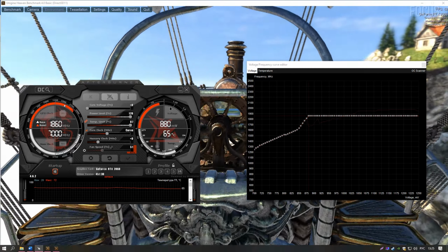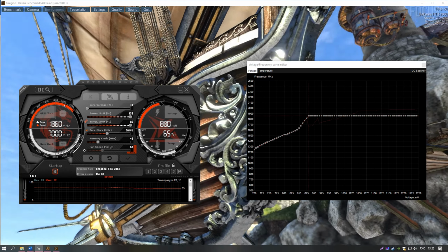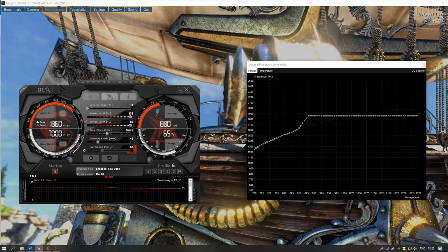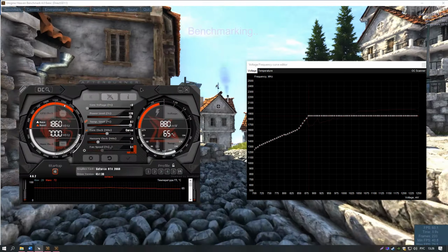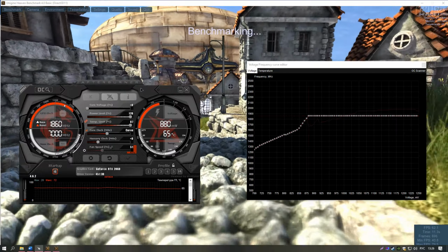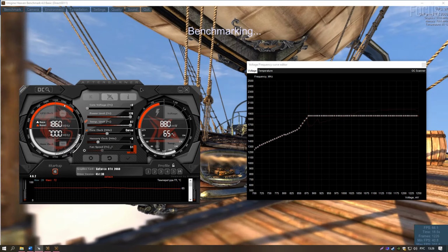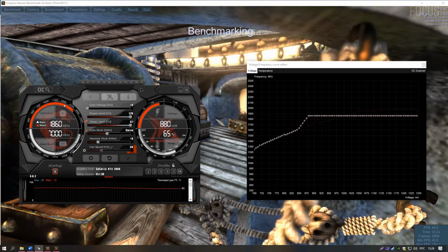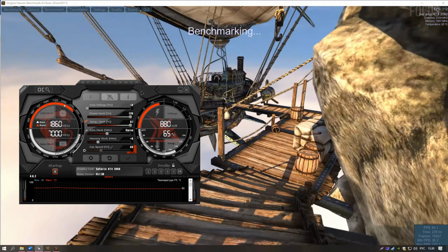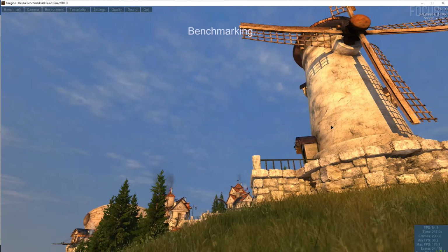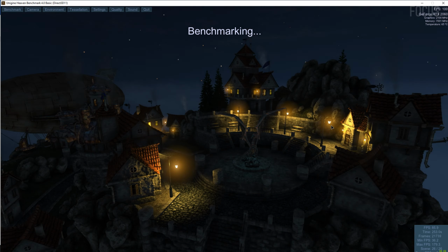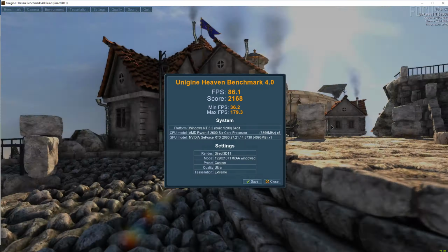In my case, the GPU is capable of holding 1860 MHz at 875 mV. However, Heaven can crash during benchmarking. Also, there is no problem in the Furmark or SST. Therefore, I will take this margin. This is the previous point, 881 mV. The difference between them in the worst case gives me about 1 degree as the maximum load of the video card. But this is not so critical.